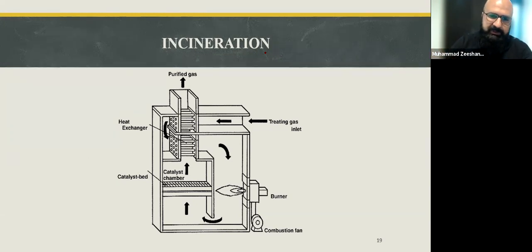So what we do is, before venting the H2S into the atmosphere, we pass it through incinerators which burn that H2S and transform that into SO2. So what we do is we have got dirty gas that enters from let's say here, and then we have got a flame over here, and that dirty gas passes through the flame, which means that it is burnt.